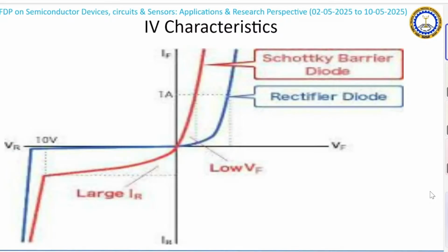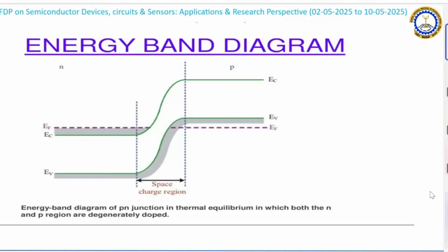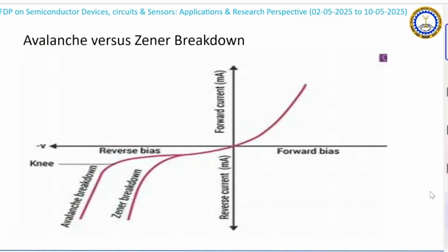The Schottky diode is very fast because a metallic junction is there. So there is nothing to hold on. The charge recovery time is reduced. And if the charge recovery time is reduced, it is a win-win situation for you. You can use it for fast applications, very high frequency applications, switching applications.